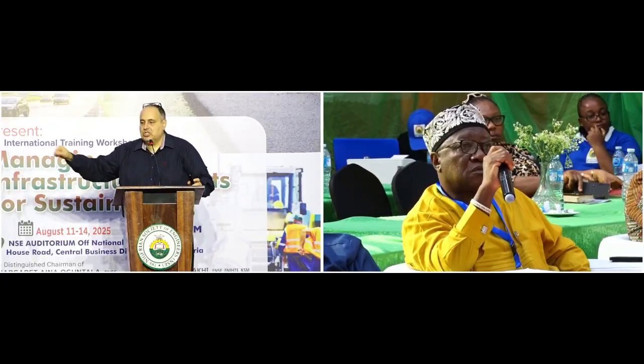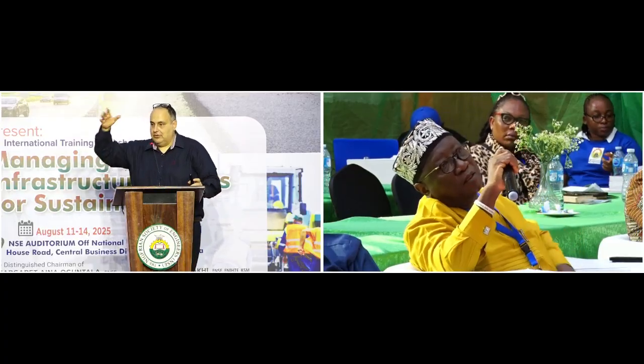You cannot put the LiDAR on a concrete pavement and tell where the rebars are. This is a GPR job, not a LiDAR job. But LiDAR can penetrate through water and do inspection, let's say for a crashed airplane that is drowned or any shipwreck down there. It can be captured.